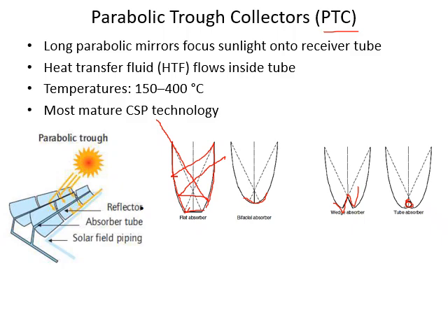We can also design it another way. For actual application we make the reflector with a parabolic curvature, then the sunlight falls on it and is reflected to the central pipe, which is called the absorber tube. This absorber tube carries the heat transfer fluid pumped through it, and it is always getting heated by the reflected sunlight.